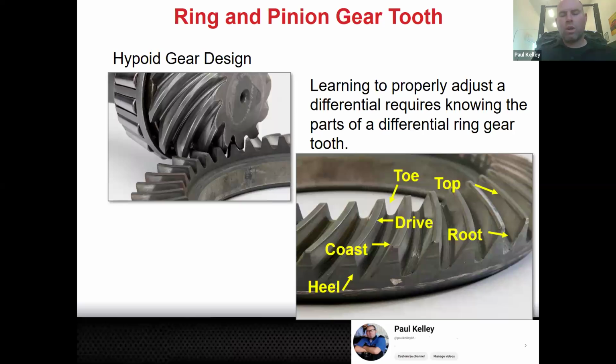We talked quite a bit about regenerative braking. It's because literally your whole vehicle is pushing your wheels, pushing your axles, and that's going to push your ring gear into your pinion using the coast side. And that's literally going to power this pinion. And we could send that pinion into an MG2 and have it become generator number 2 and generate electricity.